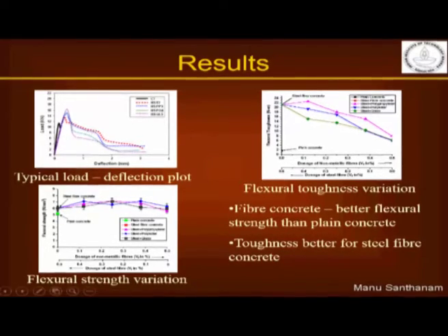So again, as we increase the replacement of steel fiber by other fibers, you see that your flexural toughness, that is the area under the stress strain curve, keeps reducing. The reduction in the area under the stress strain curve with increased level of non-metallic fiber, that means replacement of steel fiber. Nevertheless, for plain concrete, you are at a region which is somewhere very low. On the other hand, even with the plain non-metallic fibers like glass fiber or polypropylene or polyester fiber, you are at a level which is much higher than that of plain concrete.